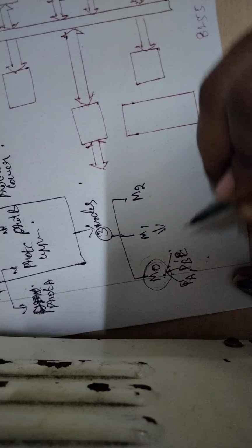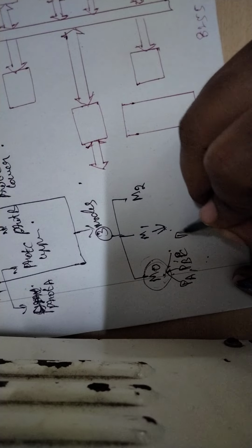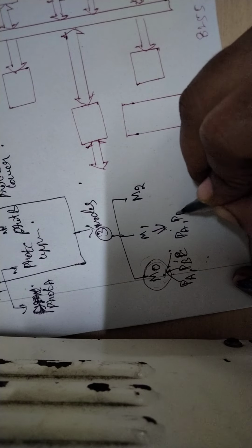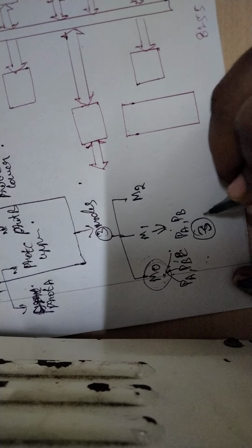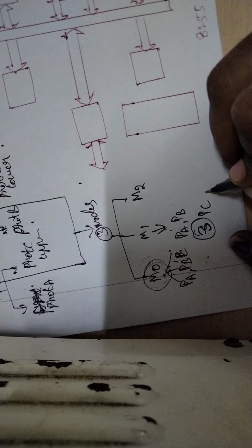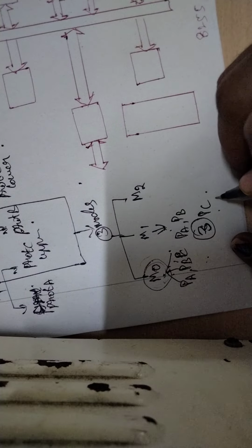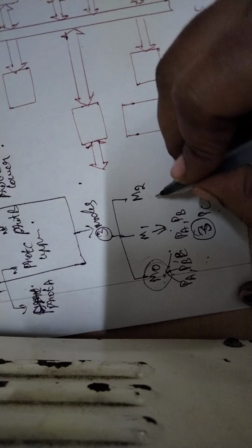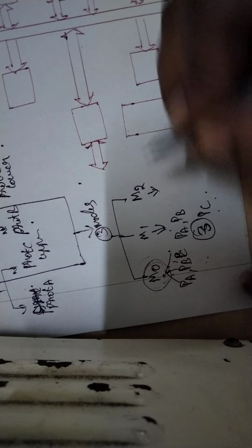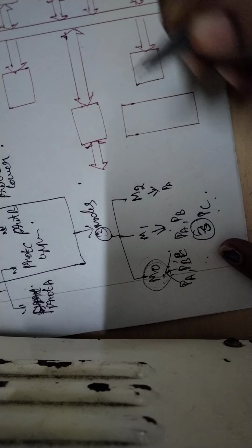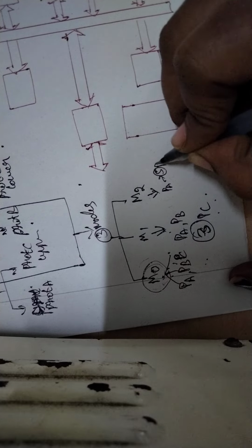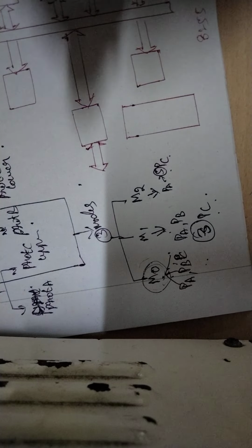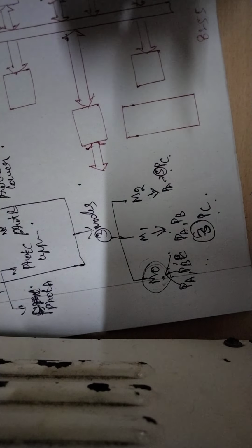Mode 1 can operate on port A and port B, and 3 bits of port C can be used for handshaking purposes. Coming to mode 2 operation, it can operate on port A, and 5 bits of port C are reserved for the handshaking signals.